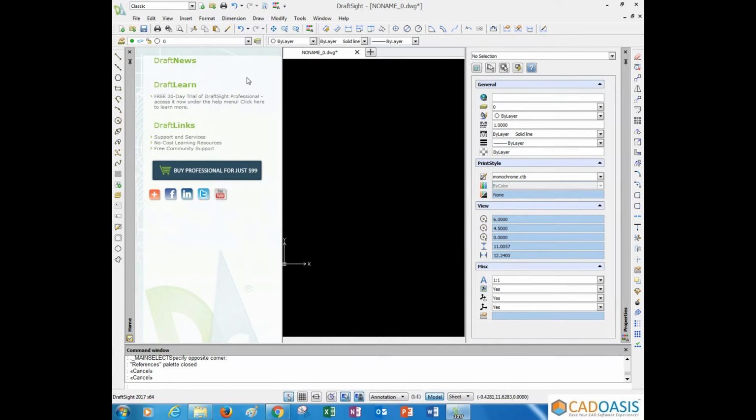Toolbars. By default, these toolbars are located at three different sides of DraftSight window. Each toolbar is a collection of related command buttons. You can move these toolbars, dock or undock any side of DraftSight window except bottom side. Simply click on the dotted line, hold down the left mouse button and move to the other side of the DraftSight window. Release the mouse button when you see this highlighted background to dock it there.